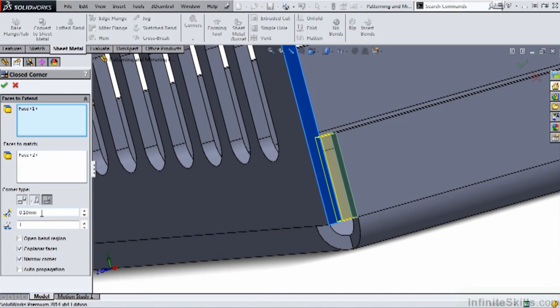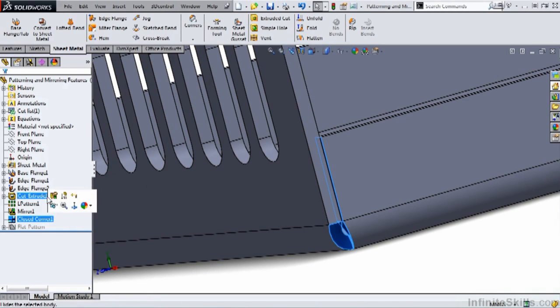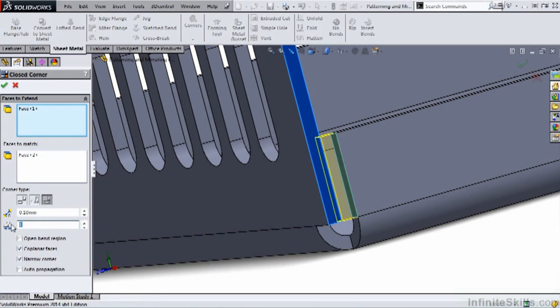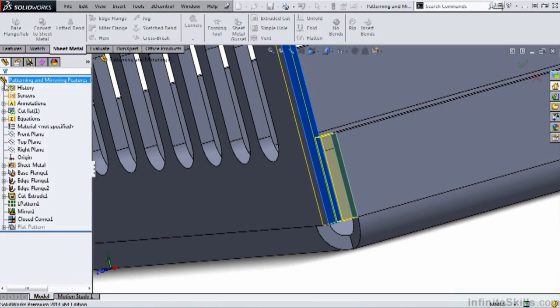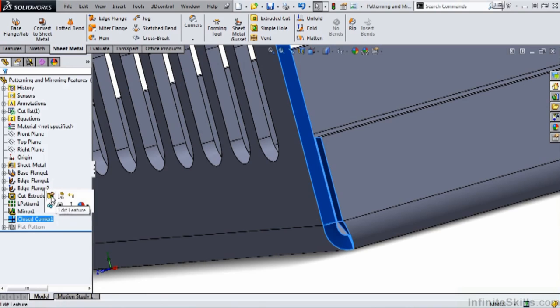Right now, it is set to a gap distance of 0.10 millimeters. And notice you can increase it or decrease it. We have another setting here called overlap underlap ratio. This value can be anywhere from 0 to 1. If I have it set to 1, I have a full overlap like you see here. However, if I have it set to 0, there will be no overlap, as you see here. So I'm going to put it back to 1.